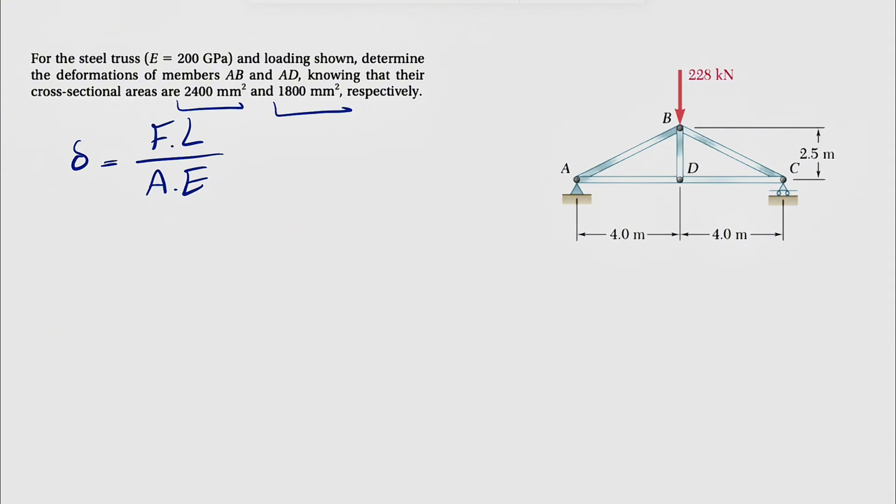Since we are in equilibrium, we can use our equilibrium equations, and it makes sense to draw the free body diagram for point A. We're going to have the free body diagram of a particle. Before moving to that, we have a pin at point A, which means we normally consider two components, AX and AY. And since at point C we have a roller, we're going to have only a normal force, or a force in Y direction. Let's call it CY.